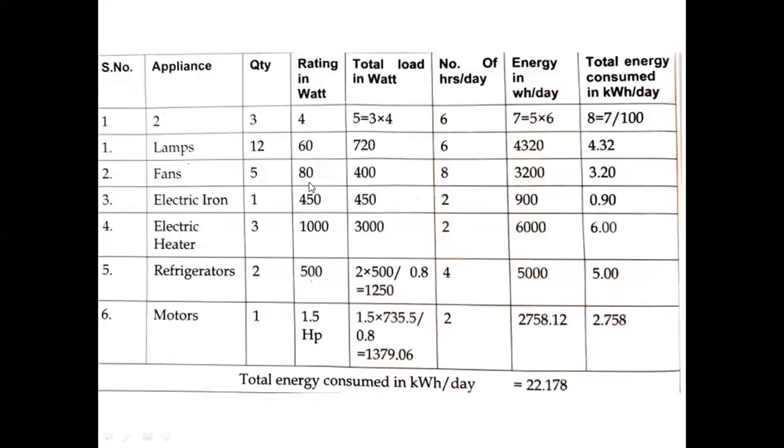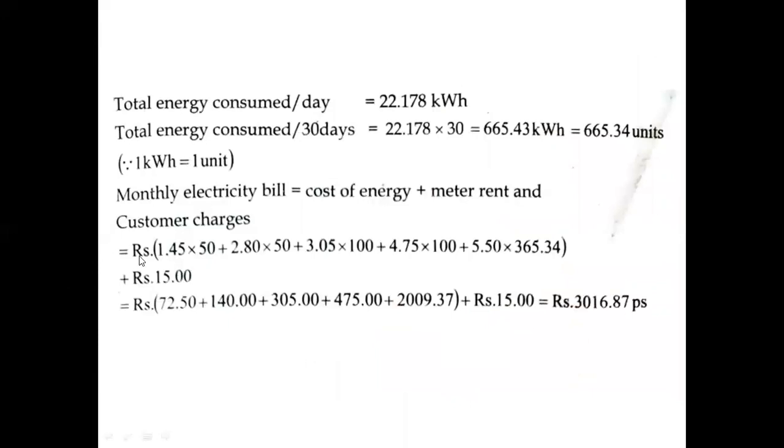Okay. So as usual, calculate the load, then watt hour per day, then kilowatt hour per day, then total energy consumed per day, 22.178. So for 30 days, 665.34.